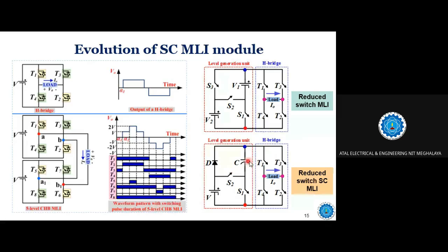But as I have just explained, this capacitor is getting charged in one level and discharging in another level. It means what? It is charging in parallel and discharging in series, right? Because of this charging and discharging, in series and parallel, in one full cycle itself the capacitor voltage will always be maintained at the desired voltage, that is the input voltage. So another interesting thing is that you can avoid the auxiliary controller; the control complexity is not there at all. You can also avoid the sensors generally required in a real-time system to balance the voltage across this capacitor.